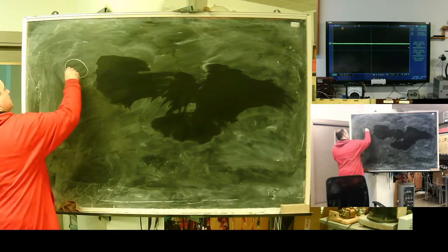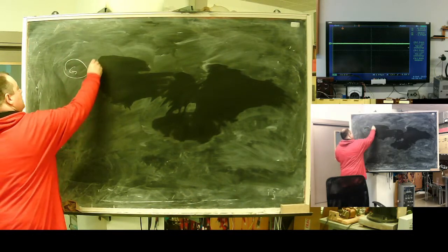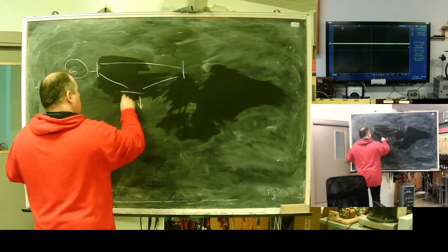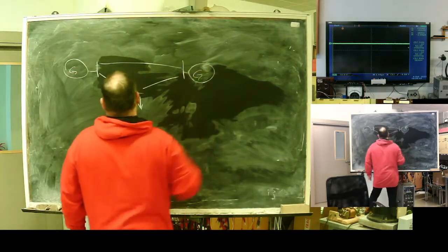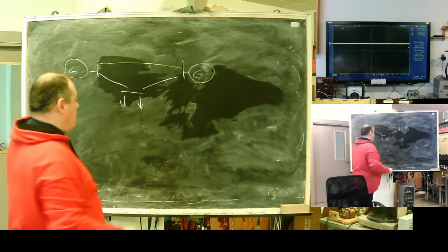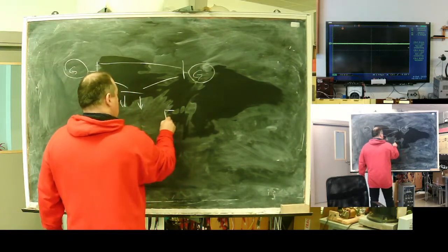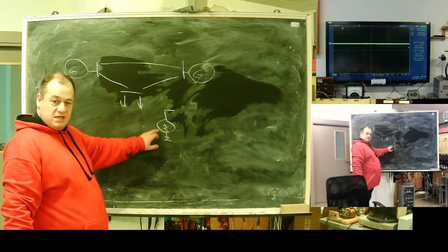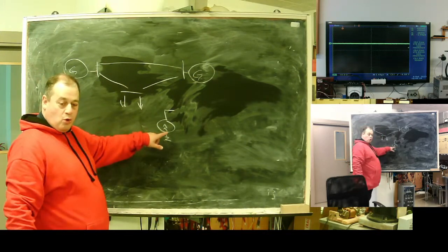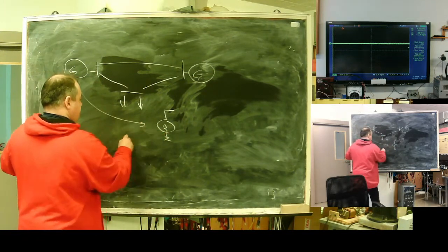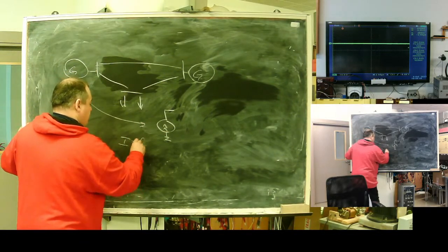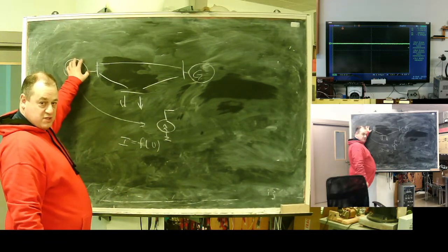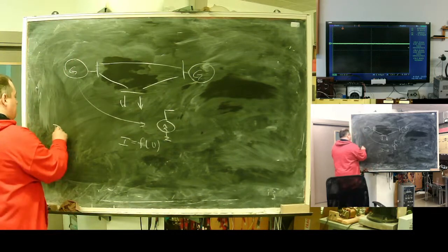So, the network is something like a generator, some power lines, loads, another generator. It will become a model like a supplying power source, it will be a current source. Its current as a function of voltage should reflect the governing control strategy of this generator. In the simplest way, it will be constant power.